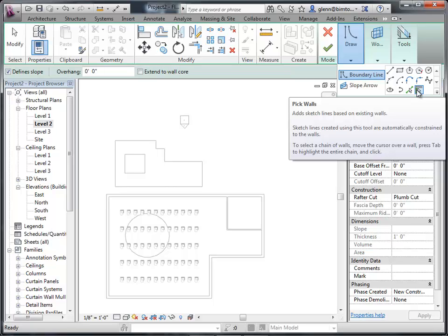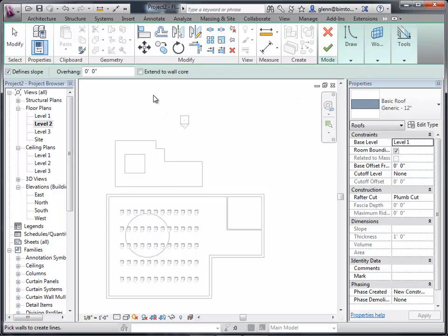So overhangs, you'll often find them on the sunny side of the building sticking out very far, and the distance really is determined by just how far out you need to be to shade the windows. Okay, so that's the general architectural rundown in terms of overhangs. We'll choose an overhang distance. We'll also choose a slope distance. As a starting point, let's put an even 2-foot overhang all around. Again, not necessarily a good choice, but it'll get us started.